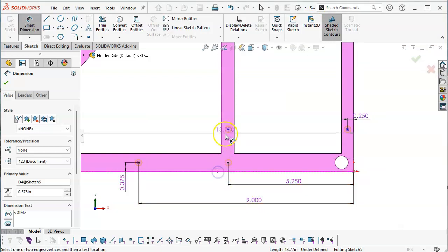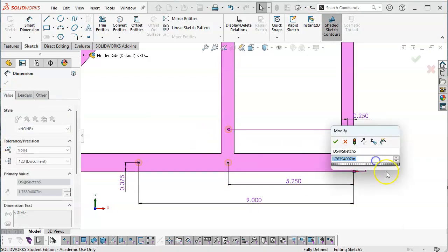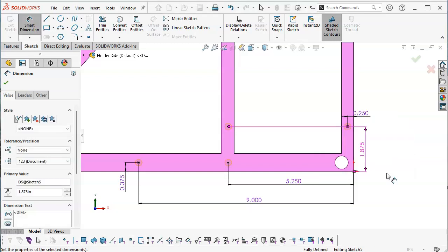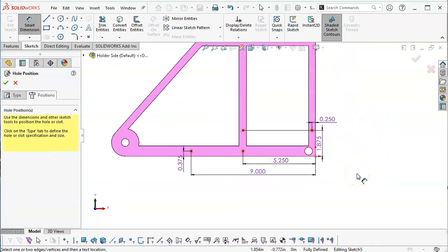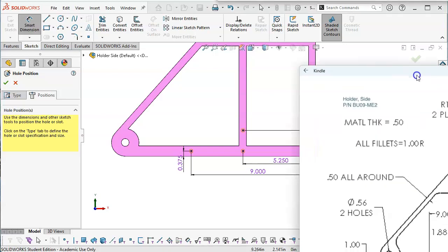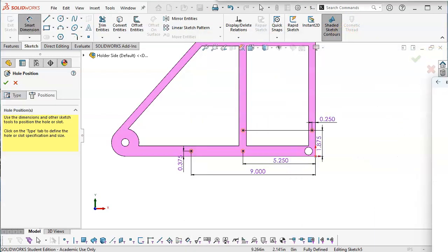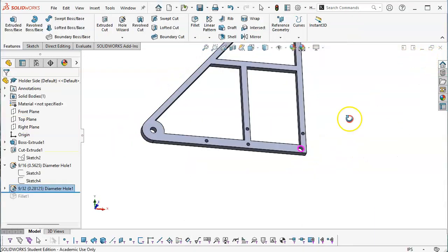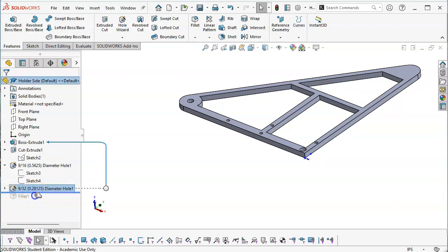So tolerance-wise, that 5 thousandths is not going to make a big difference, but you are going to have to decide if you're going to fill out those other geometries or the other decimal places to define the geometry. So we know that the fractional is 1.875, and it would round to the 1.88. So if there's going to be a mismatch in the assembly, that's one of the places that they occur. All right, so still don't know where the fifth hole or the second hole is on this group, so we'll just go ahead and accept this and roll forward to the fillet.